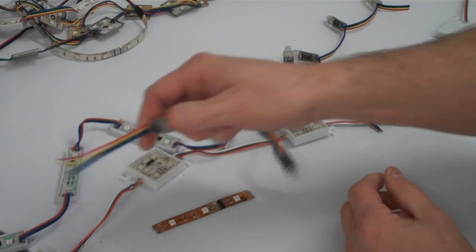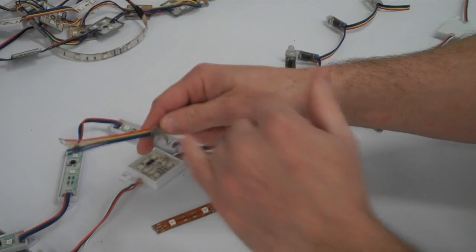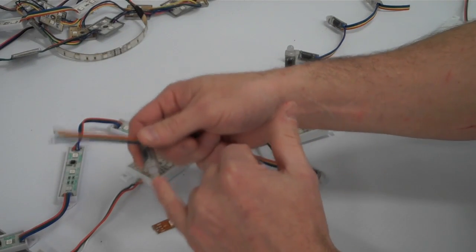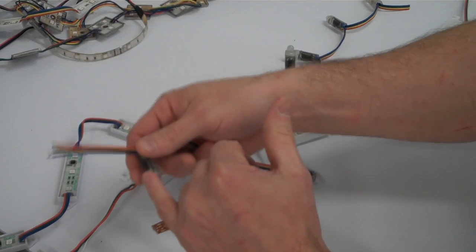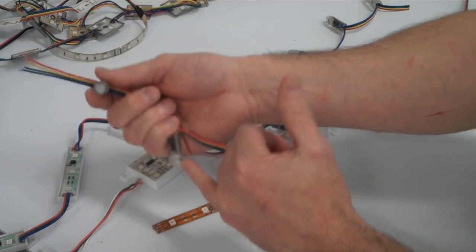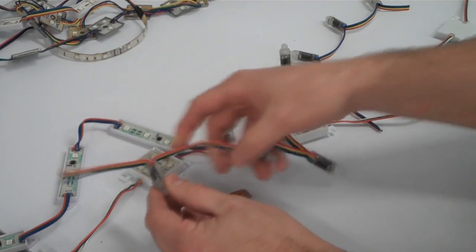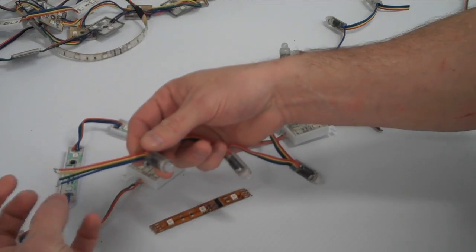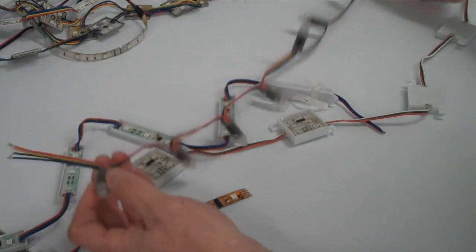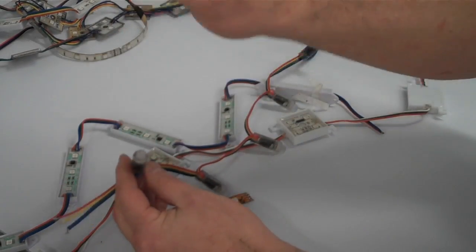Now, how does that actually map over into your software? This may physically, in the software of the controller, be pixel number 1, but it actually may be channel 200, 201, 202, and this is 203, 204, 205, again because we have 3 channels for each individual pixel. What happens is that the entire chunk of data for all of the pixels in this particular string will be sent down the line from the controller. Think of it as Lego bricks stacked on top of each other.